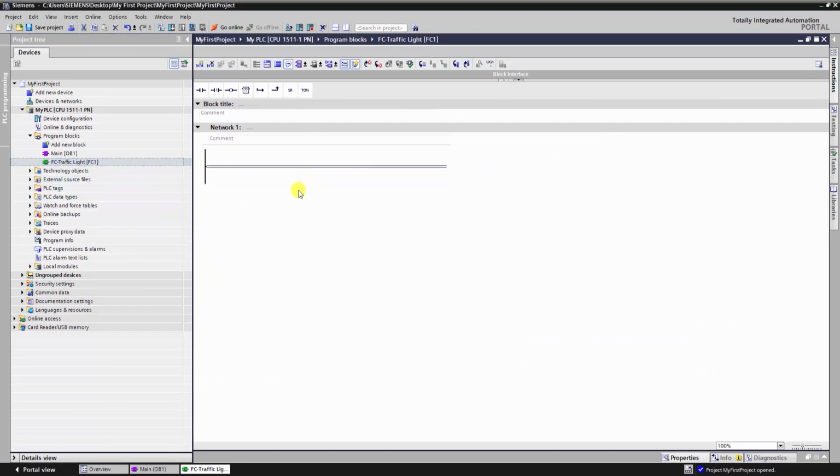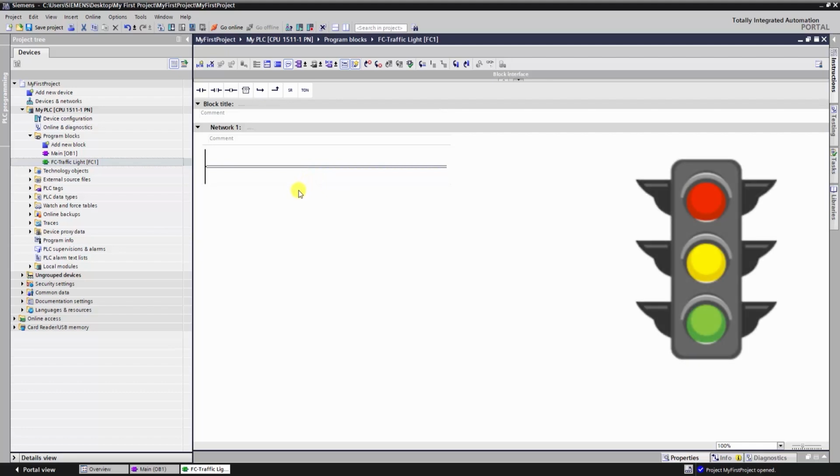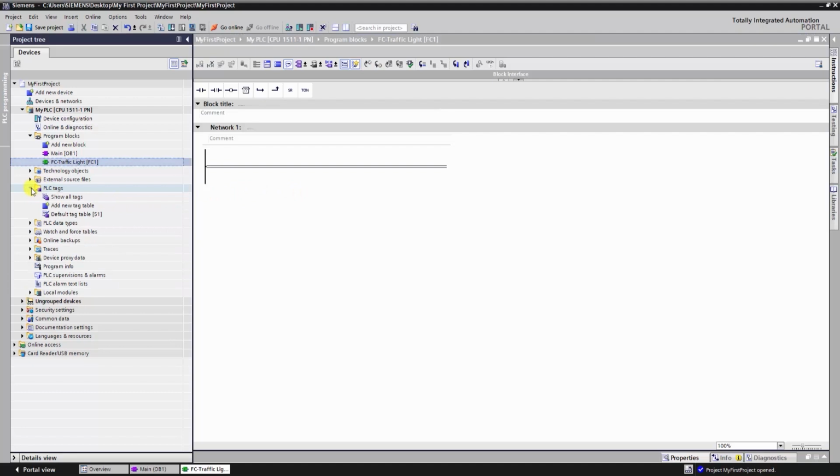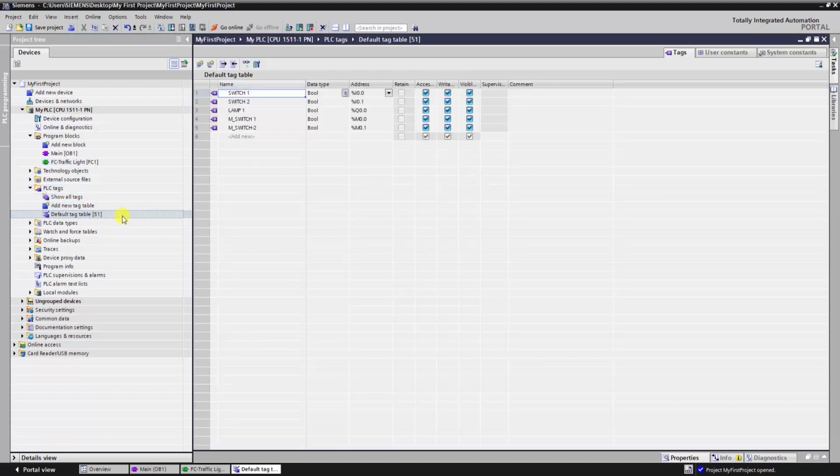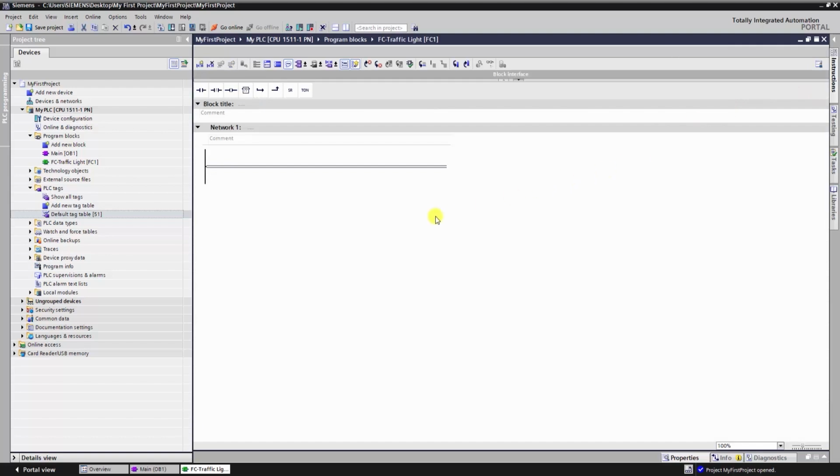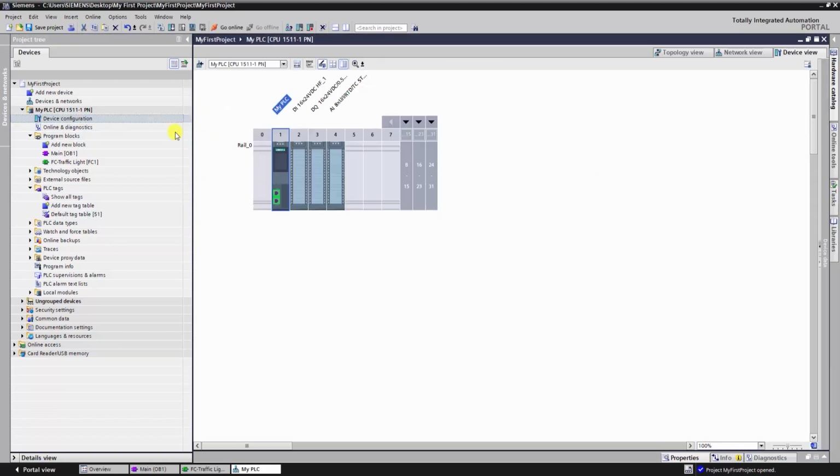The system has three outputs: the red lamp, the yellow lamp, and finally, the green lamp. We should first create these three tags in TIA Portal. They will be stored in the physical outputs category. To do this, we can either create them inside the default tag table, here, or we can define them directly through the digital output module, in the device configuration, under the section I/O tags.